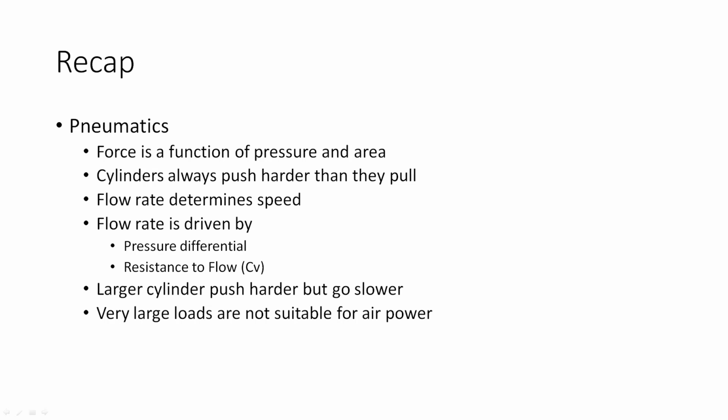Let's do a quick recap on what we've learned about pneumatics. The first one is that force is always a function of pressure times the area. If I want more force, I either need more pressure or more area. The second one is cylinders always push harder than they pull because the rod displaces area on the piston where the pressure can be applied.